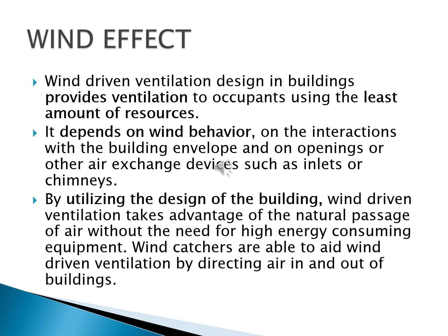Wind effect. Wind-driven ventilation design in buildings provides ventilation to occupants using the least amount of resources. It depends on wind behavior, on the interactions with the building envelope, and on openings or other air exchange devices such as inlets or chimneys. By utilizing the design of the building, such as size, shape, and the height of the building, wind-driven ventilation takes advantage of the natural passage of air without the need for high energy consuming equipment. Wind catchers are able to aid wind-driven ventilation by directing air in and out of buildings.